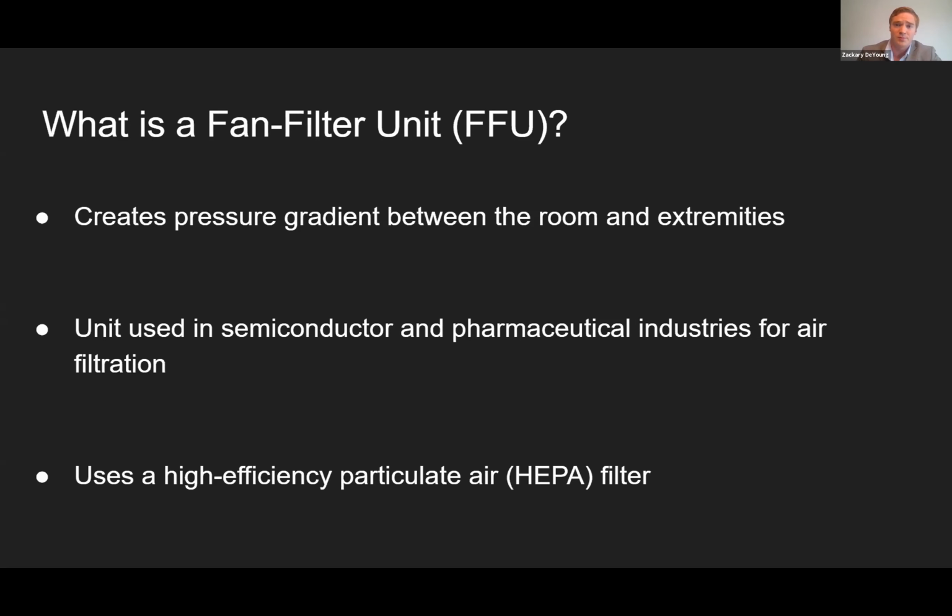The first of which to be discussed is a motorized fan, which forces air into the clean room at a rate much higher than normal HVAC settings. And this creates a positive pressure gradient between the clean room and its surroundings, which forces air out of the room and eliminates the possibility of any foreign particles entering the room from its extremities.